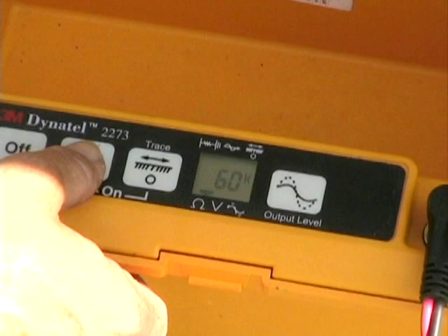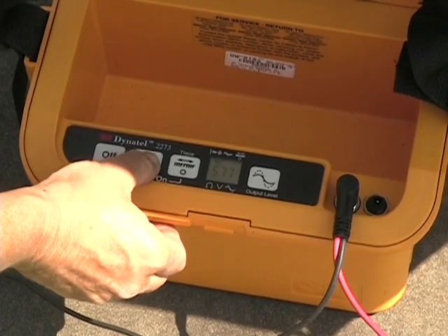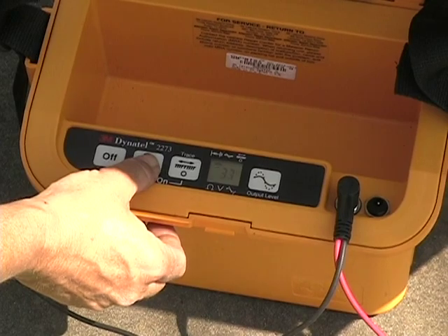The lower the resistance of the fault locating circuit, the more severe the damage is to the insulation of the conductor. If OL appears on the display, this is an indication of an open line. This indicates that there is not an earth return fault on this conductor. Press the second button on the transmitter again to place the transmitter in fault mode.